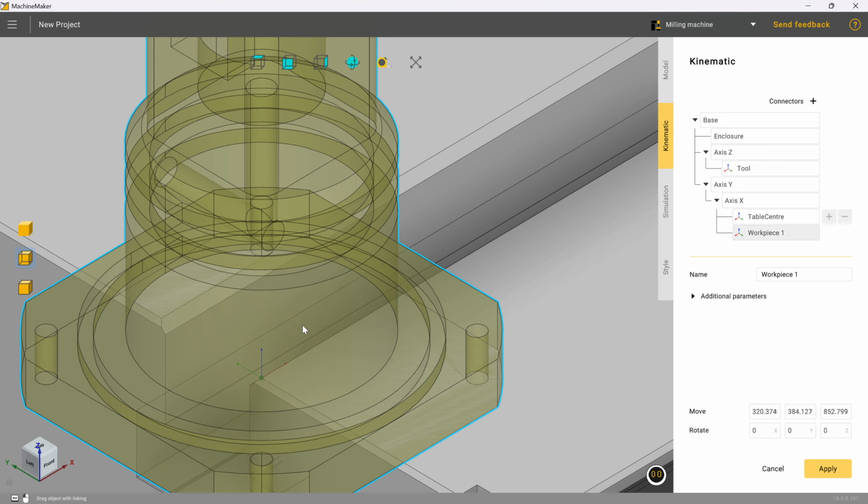So instead of best guessing it and playing around with coordinates and getting to the stage of tearing your hair out, we can use the measure tool here. And we can grab that geometry corner and this geometry corner. And we can see that it's a 19.05 millimeter T-slot, which is, if I remember correctly, 3/4 of an inch.